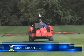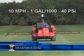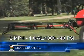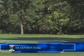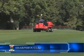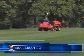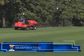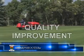SharpShooter allows the operator the option of spraying to the maximum capability of the sprayer, typically 10 miles per hour, yet it also affords the operator the ability to slow down to 2 miles per hour when the application so demands. The amazing part of SharpShooter's wider speed range capability is that it does so while maintaining a constant rate, a constant operator set pressure, and a constant, consistent droplet size and pattern. In short, the operator has increased speed range capability with an actual quality improvement.